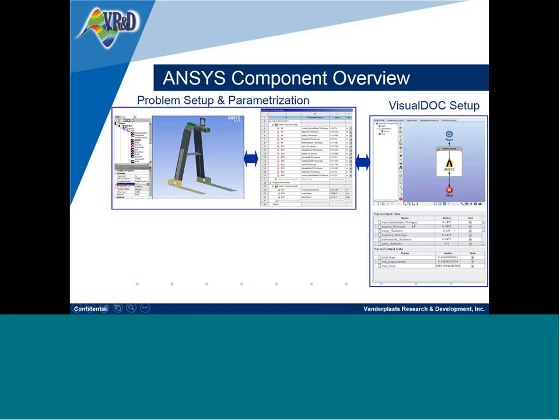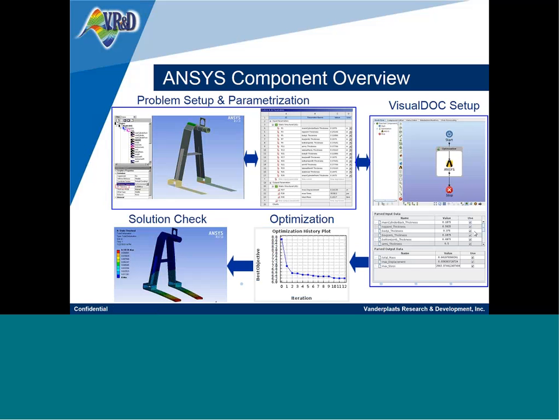One is input data, and the other one is output data. You can choose which parameters or outputs will be used in the optimization process by checking the use checkbox on the right of the table. After you set up, you can run the optimization, and after it is done, you can go to ANSYS Workbench to check the optimized structure.